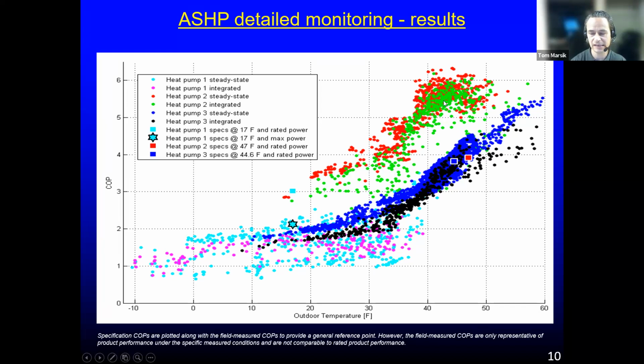So this was a ductless mini split heat pump in Wrangell, Alaska. And besides monitoring its performance, one thing that we noticed, even though it wasn't the purpose of the study, was that with a lower level of thermal loading, the coefficient of performance was going up. And what I mean by a lower level of thermal loading, just think of sizing heat pumps.